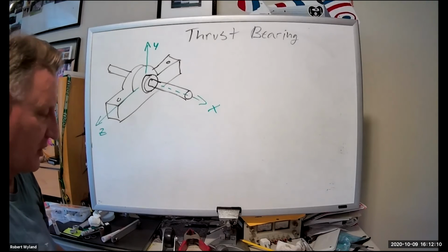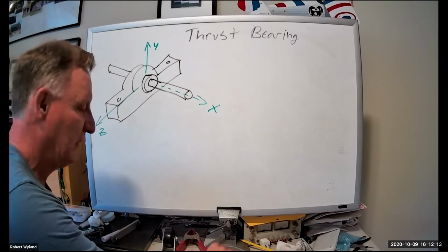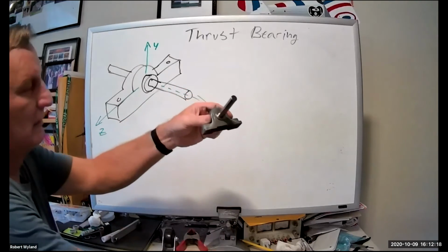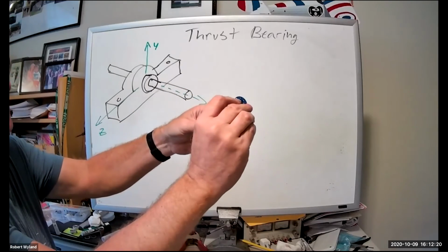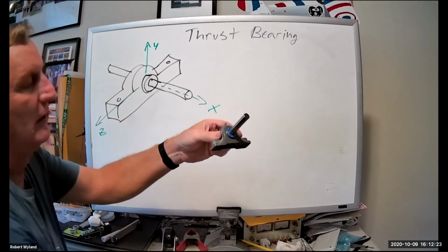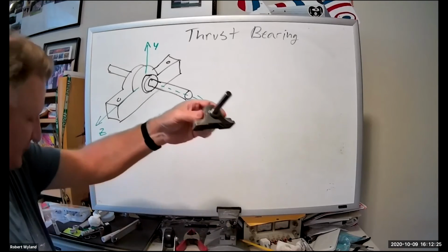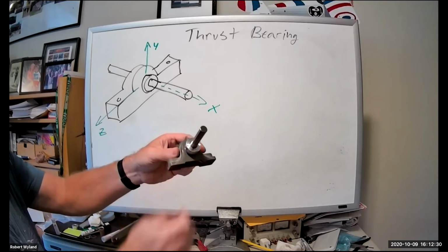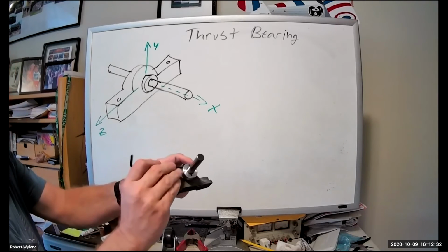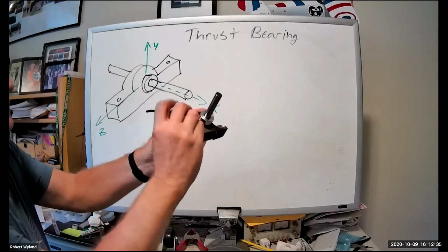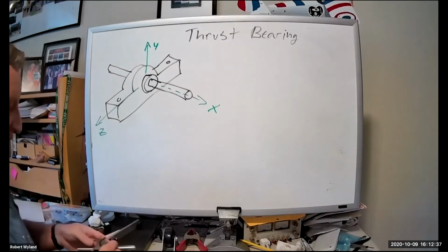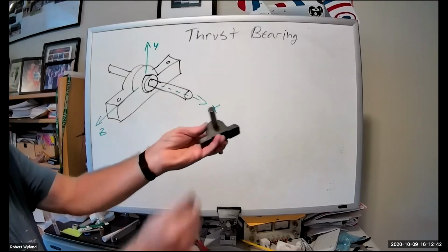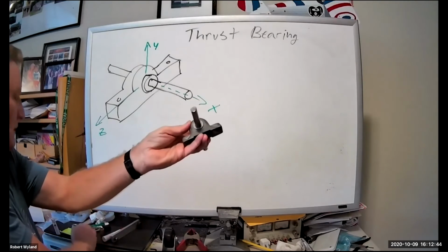So what I'm going to do is install them on my plane bearing. I slide my surface on, I slide my ball bearing surface, and then my other riding surface. And then I'm going to put a locking collar on it. Tighten that up. And then I'm going to do the same on the other side.